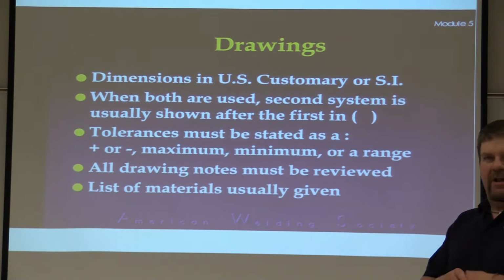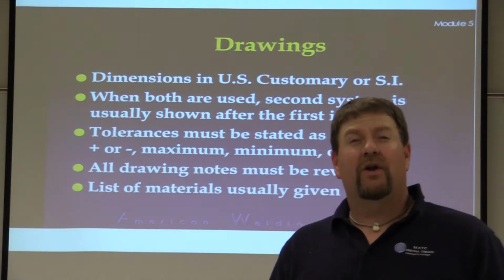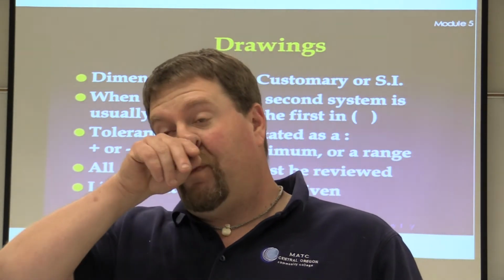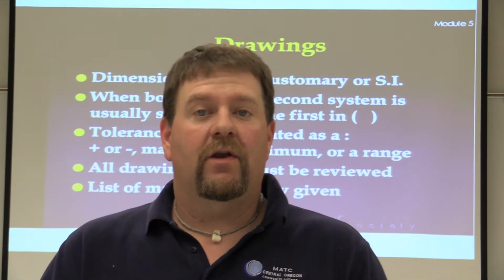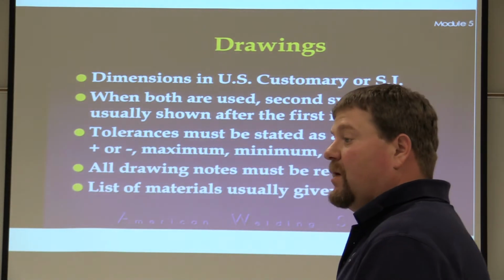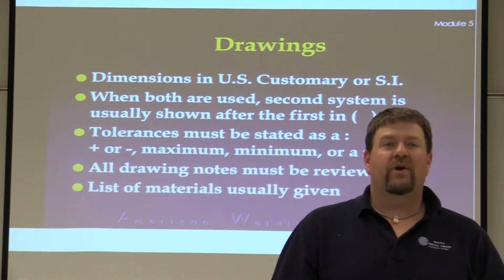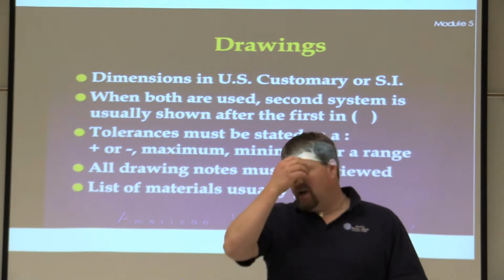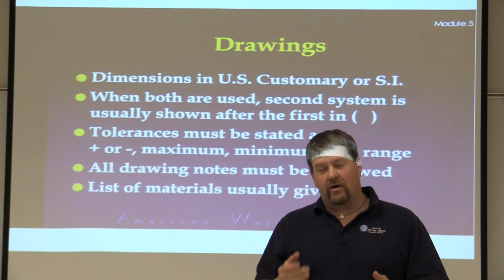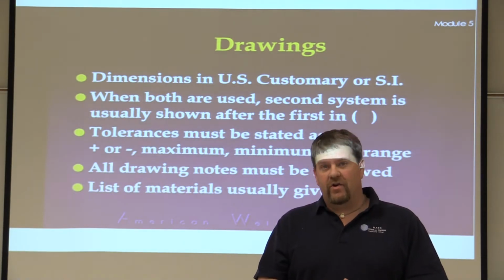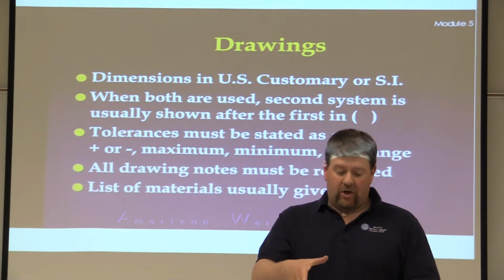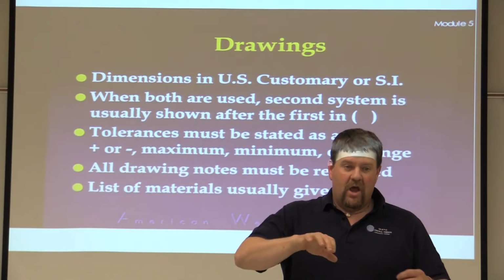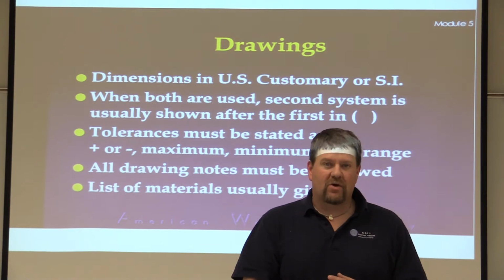So let's go back and talk about the first one, hold points. A hold point would be a good example for any of you that have done pipe in our shop, or even groove plate. I want to see the root before you continue on, right? So there's a perfect example of a hold point. Say you've done 3/4 of the weld pass of the pipe that's contained, and it's not going to get an NDT shot, so it's not going to get x-rayed or ultrasounded. It all has to be done on visual. Then I'm going to inspect. I want you to leave 1/4 of that pipe open for a visual window for me to go in and inspect it. And then I'm going to watch you put the last 1/4 of that weld in.